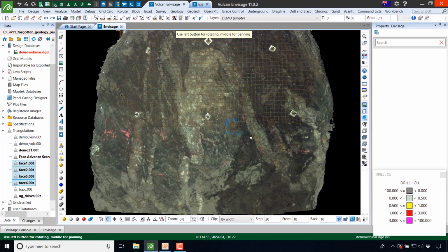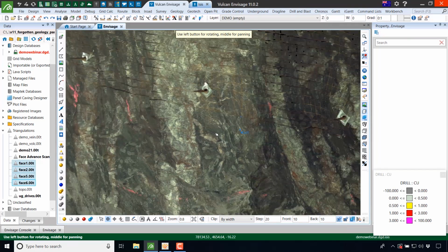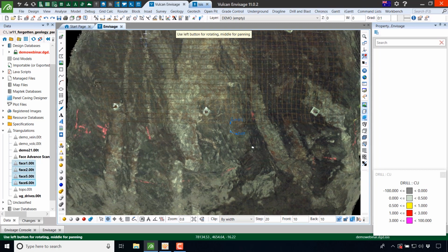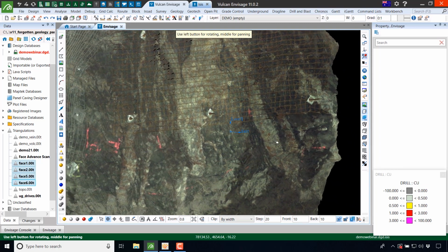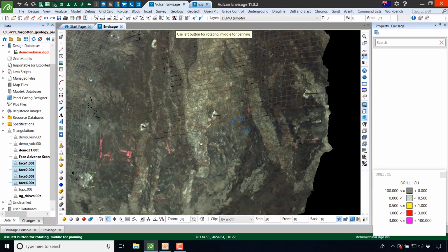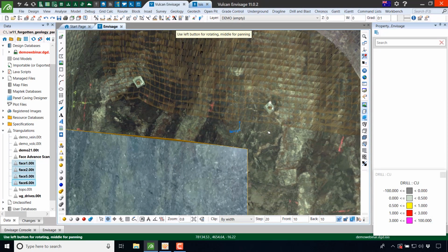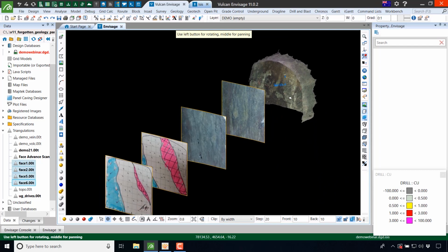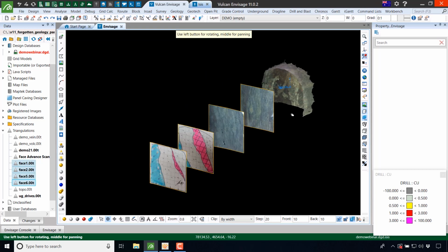So this is an image scanner that takes not only the geometry, but also a very detailed geology photo. I think in this case it was about a 130 megapixel image, and the point spacing on the geometry here is between 1 and 3 millimeters, so extremely accurate. And they too can be used, as you can see, to just digitize in 3D and incorporate that data. So again, we've got 3 levels of information, from the fairly basic, a little bit better, to you can't really get much better than that technology there.